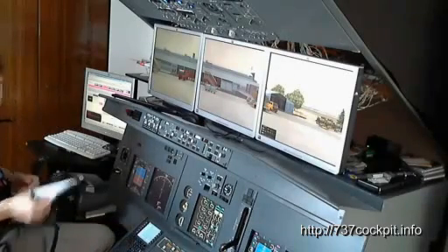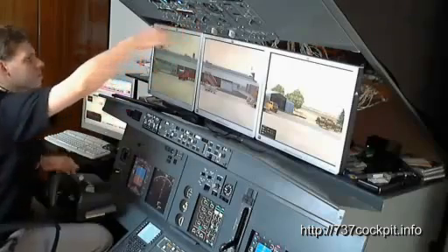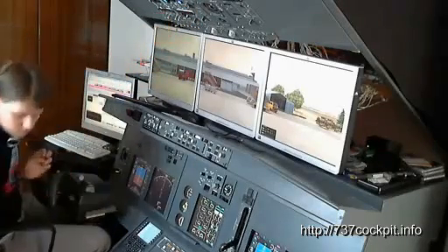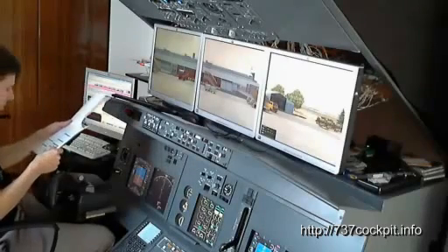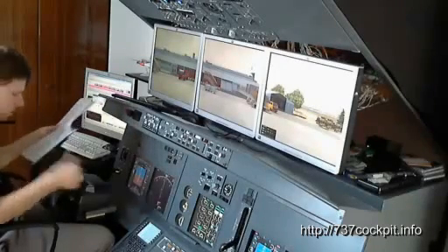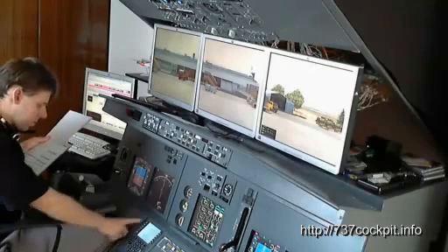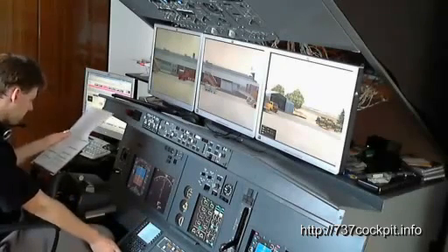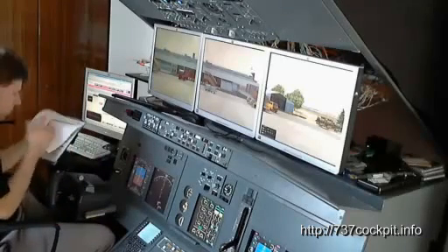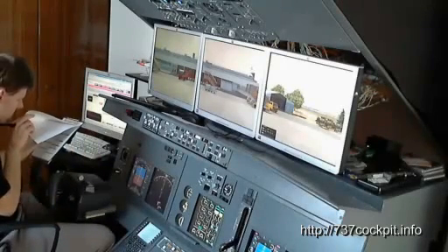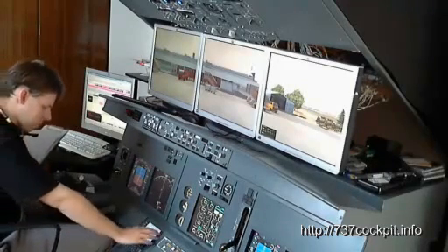Standard instrument departure: we have fully completed and are also ready for startup. That means our next checklist is the before startup checklist. We have the FMC set. Our N1 box is set, flaps 5. That gives us the calculated V speeds: 137, 138, 138.